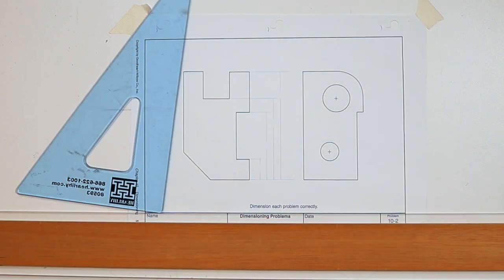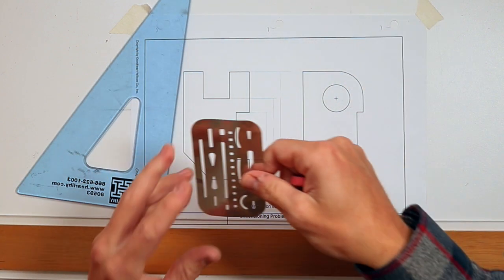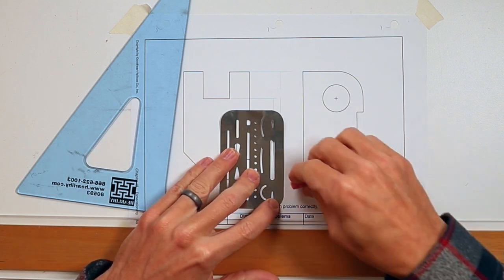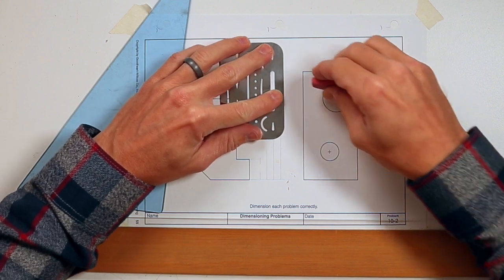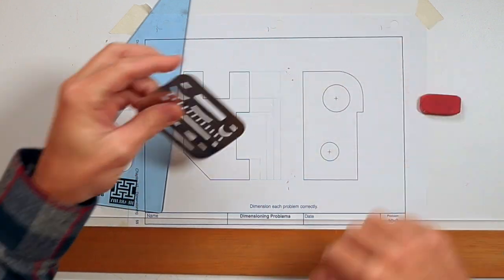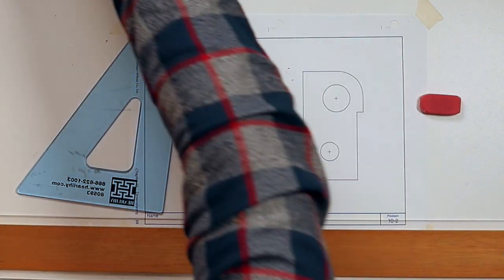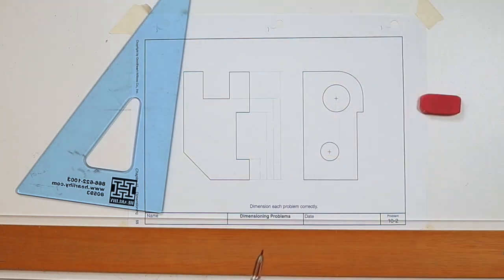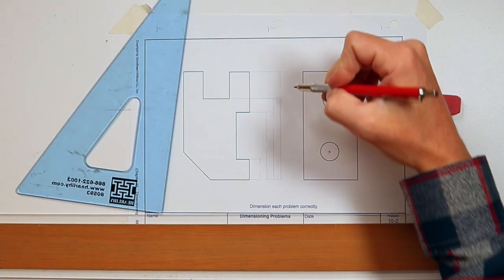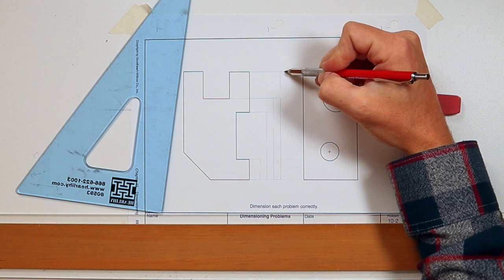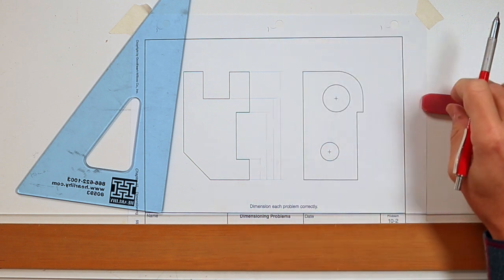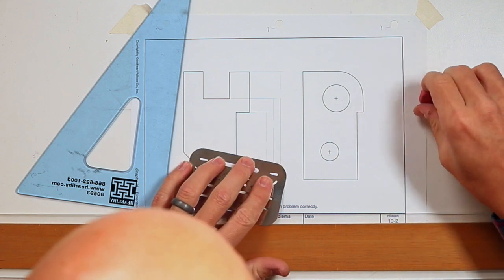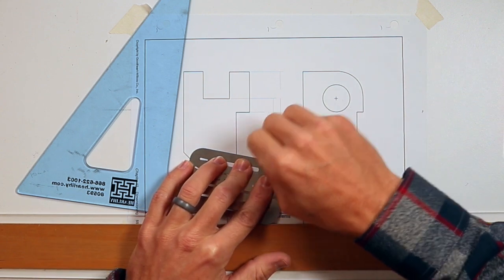Alright, so now, before I get any further, I'm going to put my arrowheads in last, but I'm going to shorten my extension lines. So what I first did was, I erased the end of the extension, because it should only sit past this last dimension, 1/8 of an inch. Then these are the same way. I have a little bit of an issue right here. I'll fix now.